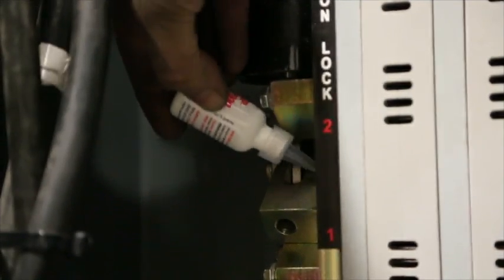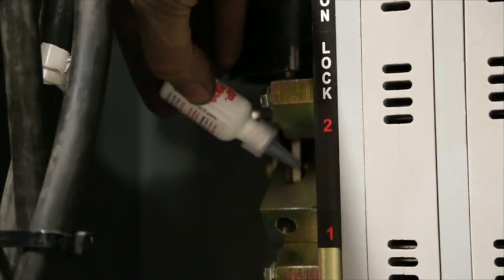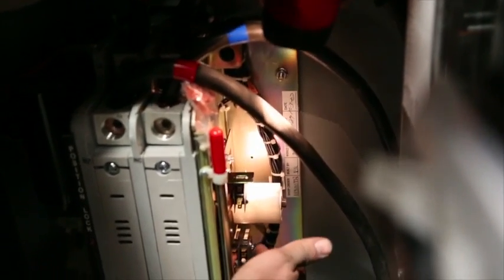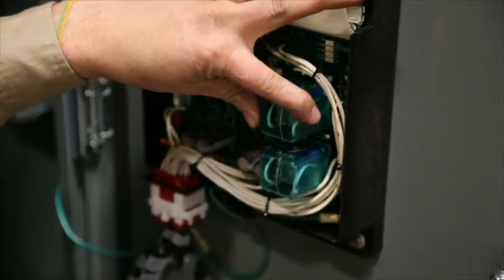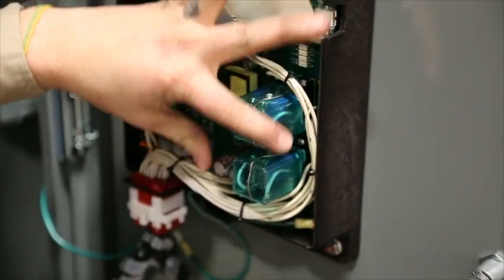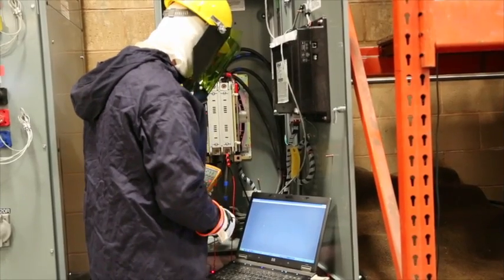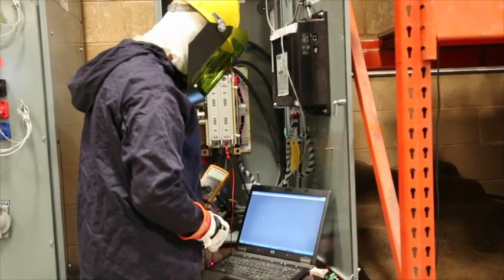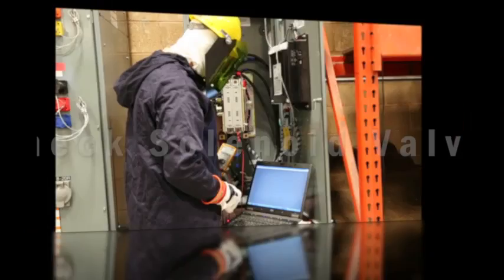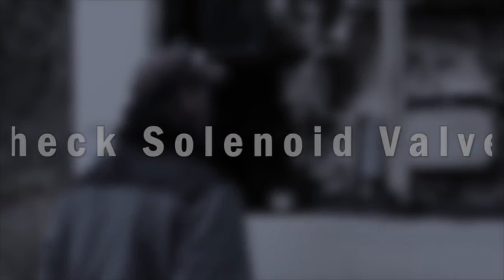Check and lubricate the switch and look for any binding. Check and retorque the ATS mounting hardware. Check and retorque the ATS contact mounting. Check, inspect, and clean the controller and its relays if fitted. Check the calibration of the voltage sensing circuitry and set points and recalibrate if necessary. Check solenoid valves for proper operation, if applicable.